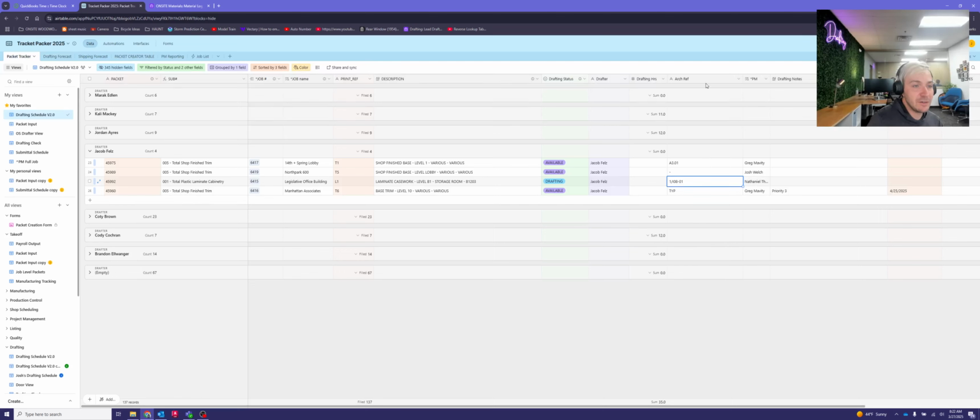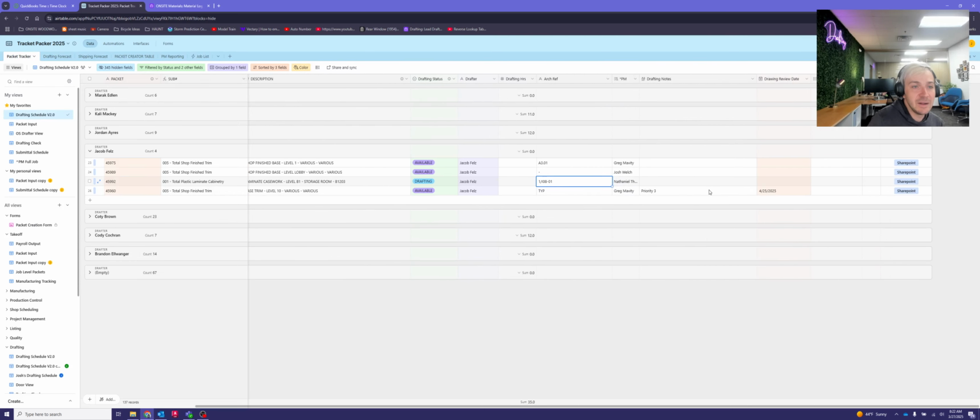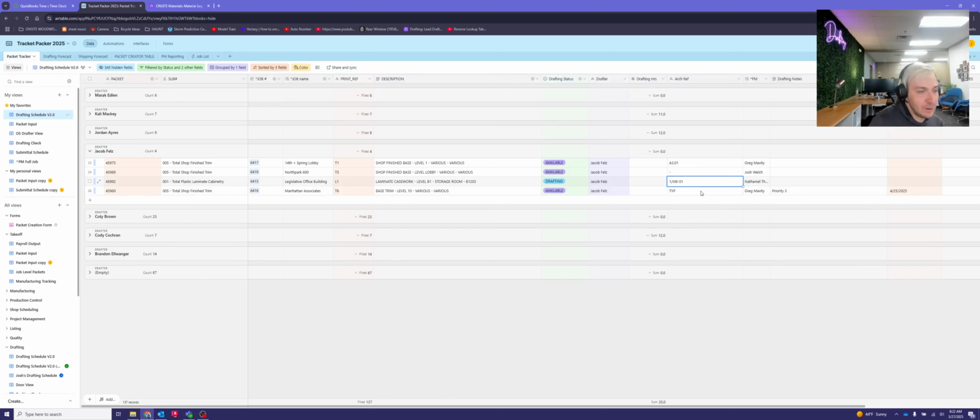To the right of that, you're going to see the architectural reference. This is really important because it's going to take you to the drawing where the elevation view that you're working on is located. So we're going to be looking for view number 1 on page I08-01. We'll keep an eye on that in just a sec. And there's nothing else to take note of here as we look at the list. So